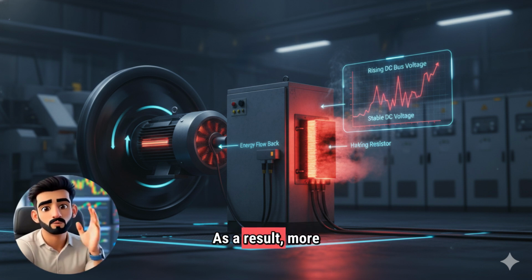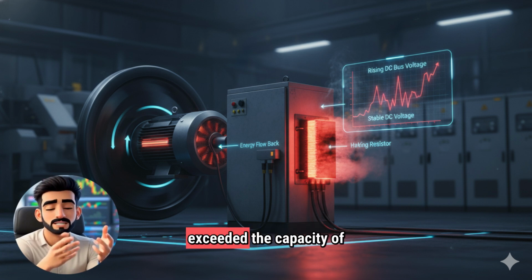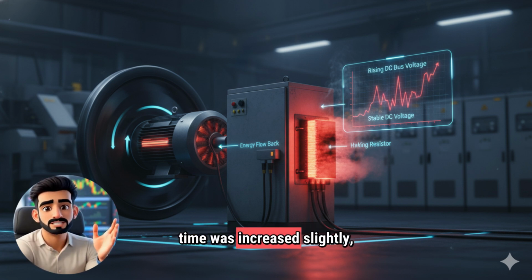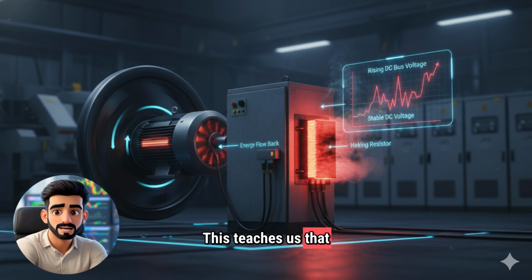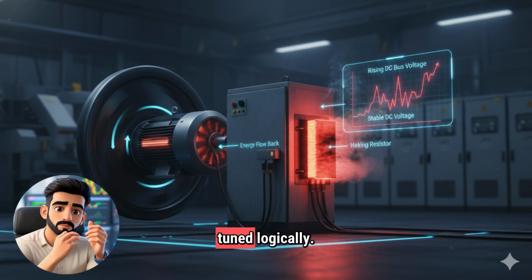As a result, more energy was returning to the DC bus in generator mode, which momentarily exceeded the capacity of the braking resistor. The engineering solution was simple. The deceleration time was increased slightly, the braking resistor selection was verified, and the system became stable. This teaches us that adding hardware alone is not a solution. Parameters also need to be tuned logically.